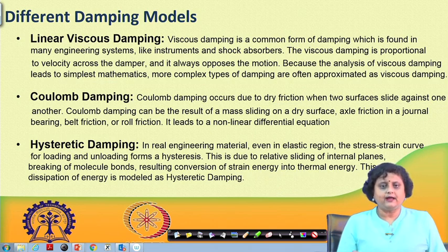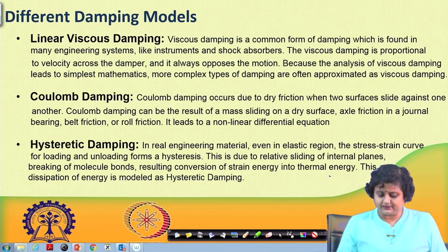One point I want to emphasize is that damping is a dissipative force which takes away energy from the system, and if a system has damping, then conservation of energy does not apply to the system. We have to always consider the dissipative force if we are considering conservation of energy. Second, most of the real cases are underdamped. Critical damping and overdamping are rare cases, and linear viscous damping is probably one of the most common forms of damping. So, let us now go into certain examples.